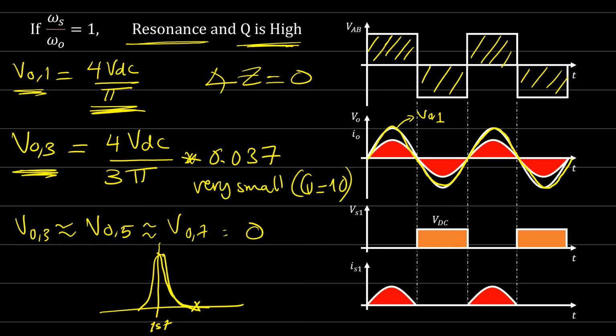If you look at switch number 1, you'll find that its voltage is 0 when it's conducting, because at this point we said switch 1 and switch 2 are on. And here switch 1 and switch 2 are off. When switch 1 is off, the voltage across switch 1 will be how much? VDC. And the current will be, of course, 0.